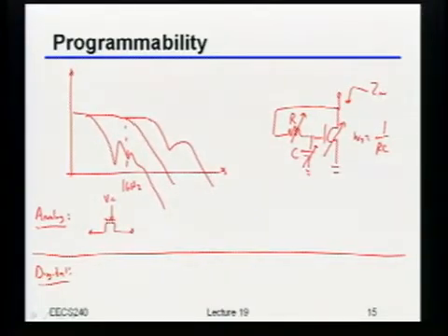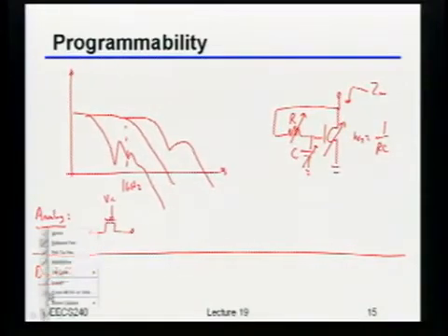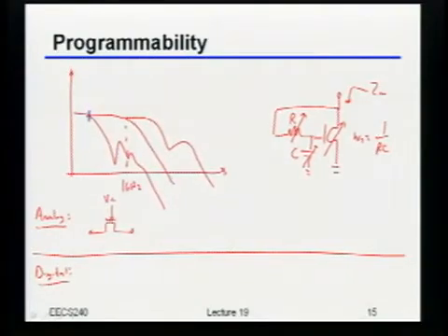Now, the only problem is that because it's based on the device characteristics, when I move that gate voltage around, I may not know exactly what I'm setting the resistance value to. So you'd have to come up with some feedback loop that tells you what magic voltage you need to set your equalizer zero to sit somewhere over here, let's say. So that may be a little bit of fun. If you're interested, come bug me. I can show you a couple of ideas.